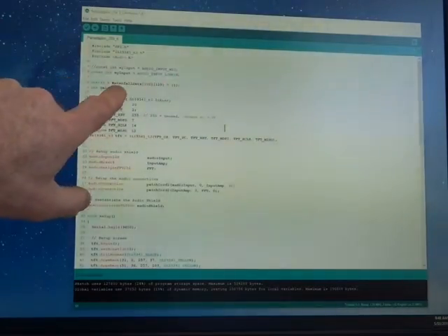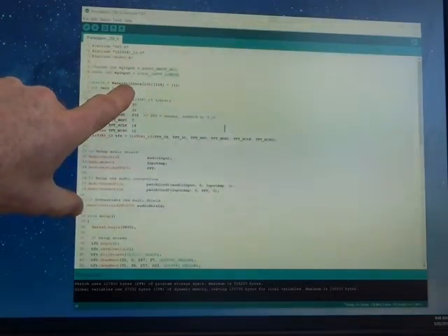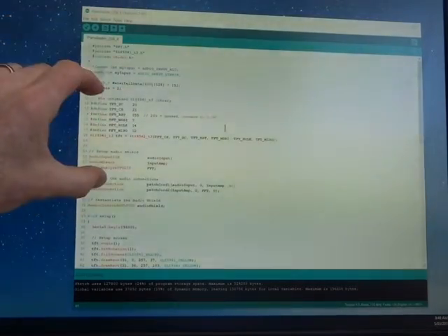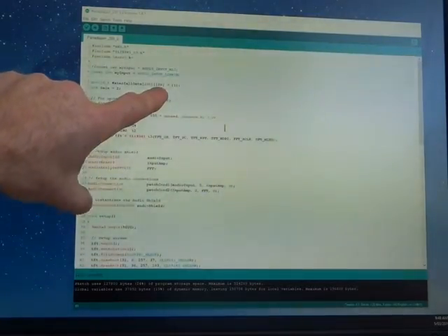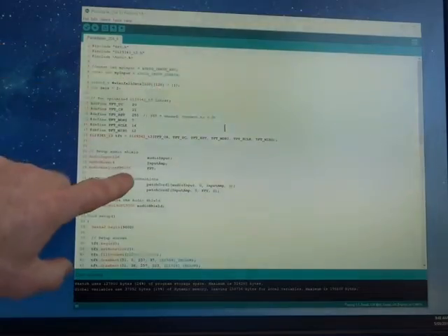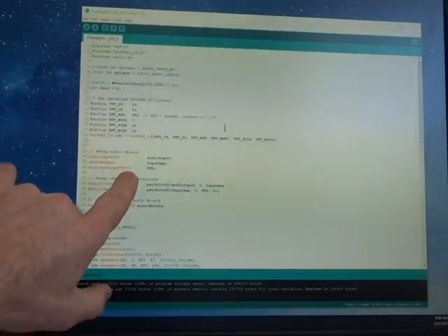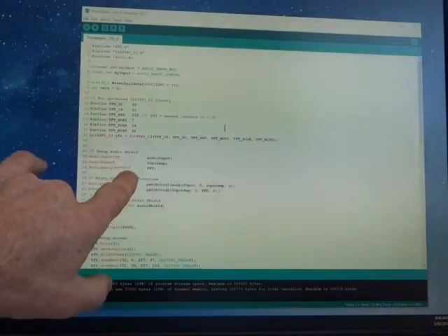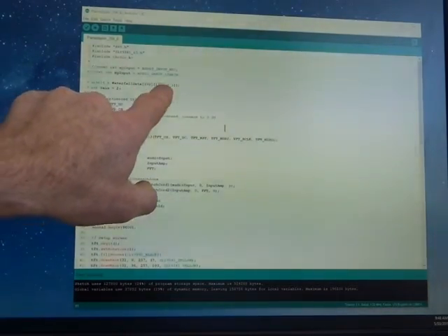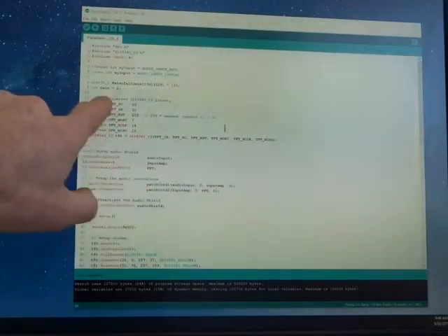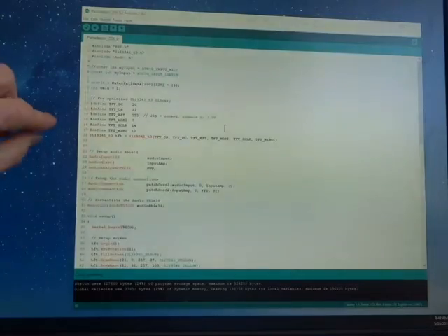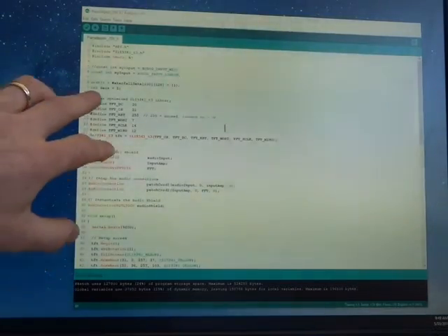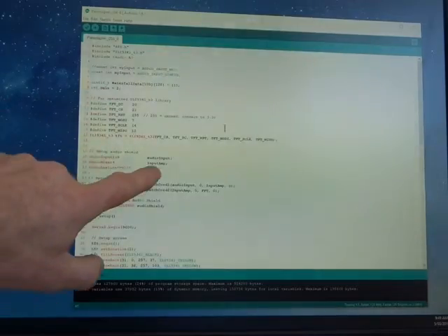I've got what I'm calling a two-dimensional array here, the waterfall data. It's 100 deep in that direction, and it's 128 wide. I'm using 128 at this point because I'm playing around with the 256 point FFT, so I'm just looking at those first 128 bins. Therefore the width of my array is 128. That gain there is just notionally what I'm using to adjust that input amplifier. It's a quick way of being able to, in software, vary the amplitude of the audio coming in before it gets analysed by the FFT.